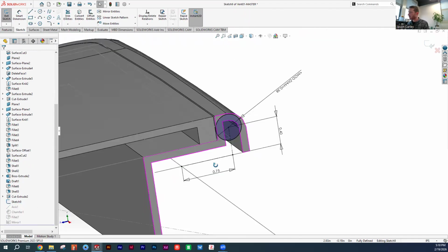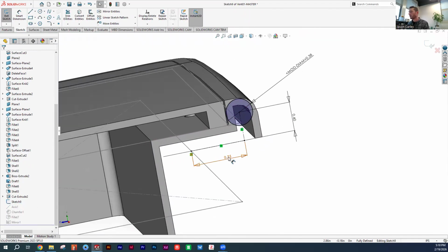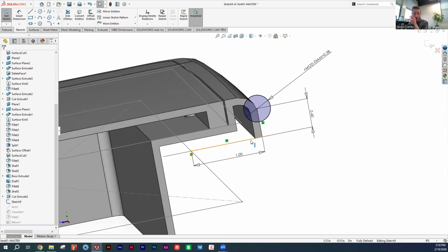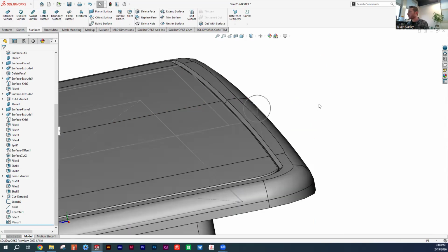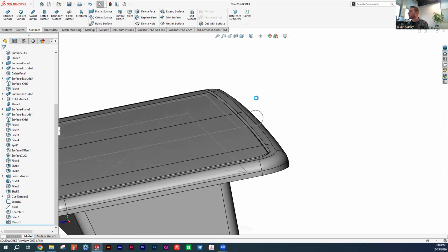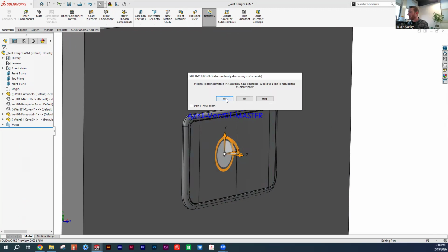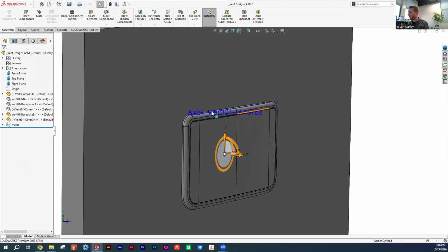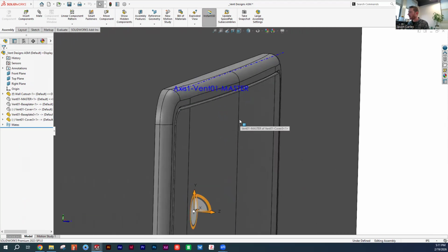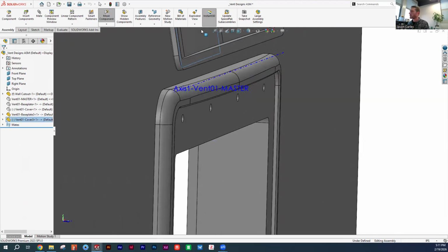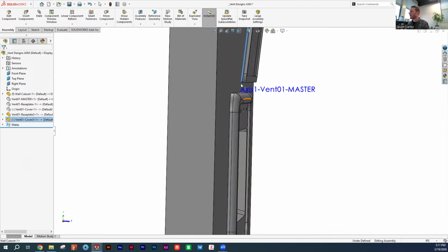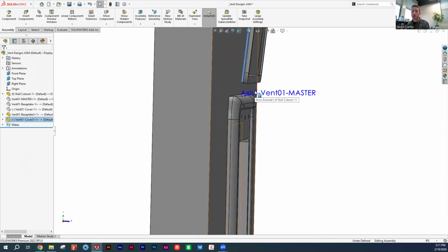And let's say I wanted to push this hinge point out a little bit. Let's say I overbuild the feature, I can add some more material over here, and I can have an offset hinge. I don't think it'll look that good, but it'll make for a nice demonstration. So I hit check, I hit save. I can go back to my assembly. I rebuild. I don't see anything change in the viewport, but I'll see it change once I start to swing my door. Now I see that that hinge has changed.